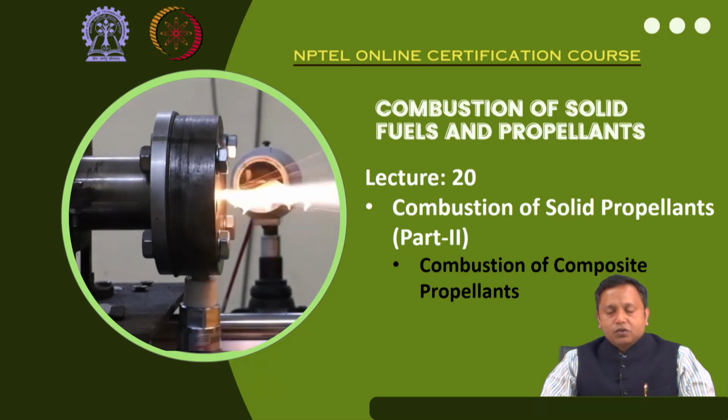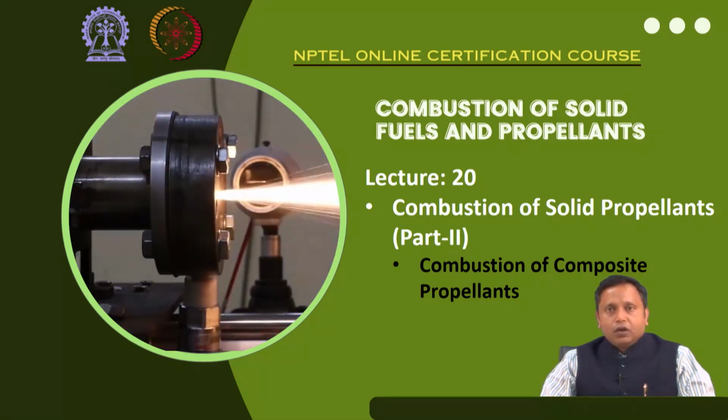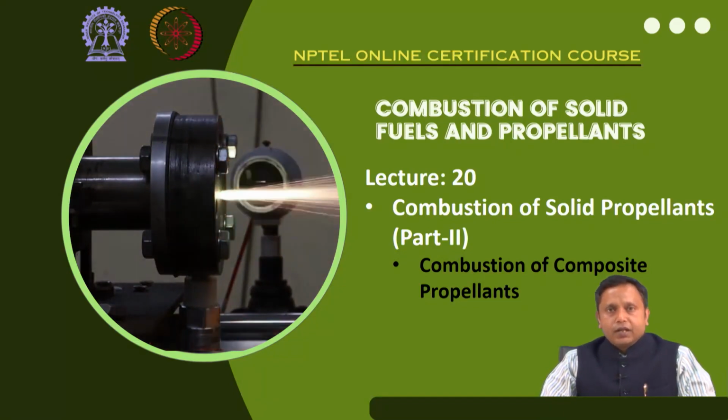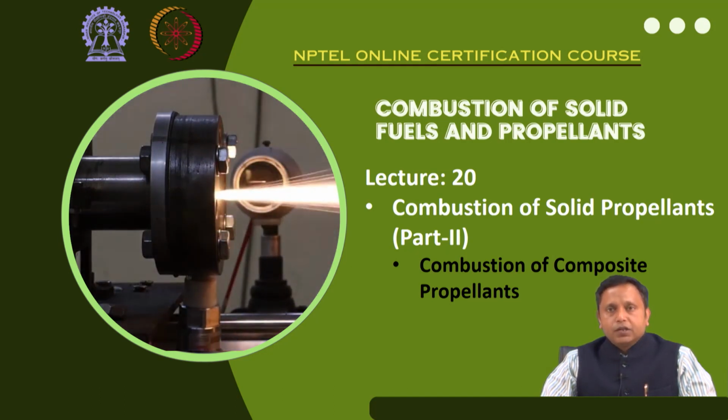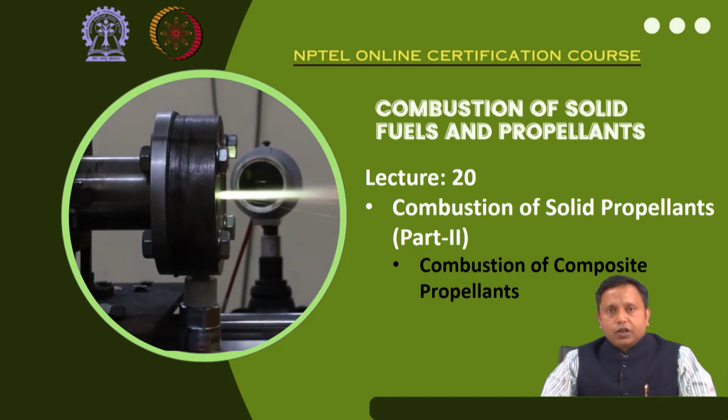Hello everyone. So, we are continuing our discussion on combustion of solid propellants, and in the previous lecture we have begun our discussion on combustion of composite propellants. We have discussed thoroughly the various ingredients used in composite propellants, and we have said that the decomposition of oxidizer plays a very important role in the combustion processes of composite propellants. And we have also talked about that ammonium perchlorate is considered to be the workhorse oxidizer for composite propellants.